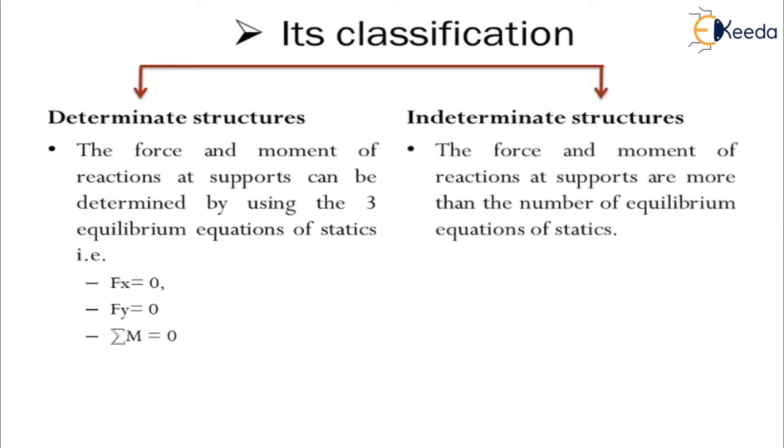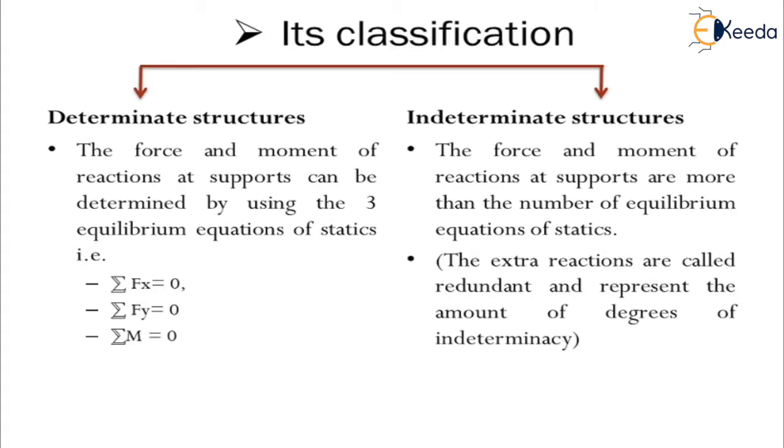Indeterminate structures are the structures in which the reaction forces and moments cannot be easily found out by equations of equilibrium of statics. The extra reactions are called redundant reactions and they represent the degrees of indeterminacy.